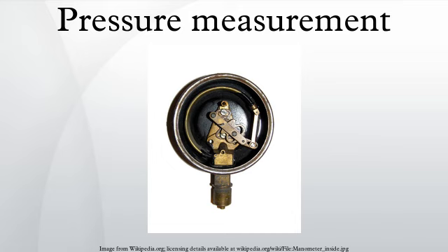ion beam. This ion beam can be passed on to a Faraday cup, microchannel plate detector with Faraday cup, quadrupole mass analyzer with Faraday cup, quadrupole mass analyzer with microchannel plate detector Faraday cup, ion lens and acceleration voltage, and directed at a target to form a sputter gun. In this case, a valve lets gas into the grid cage.